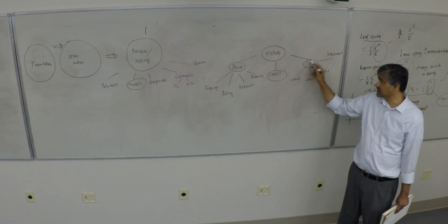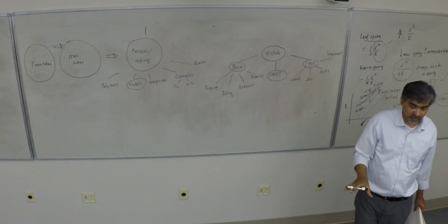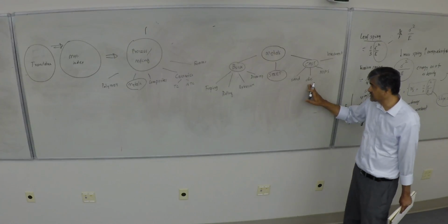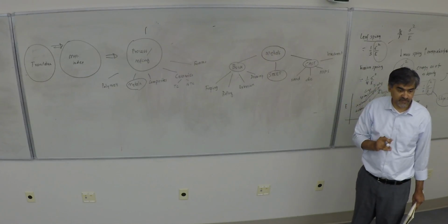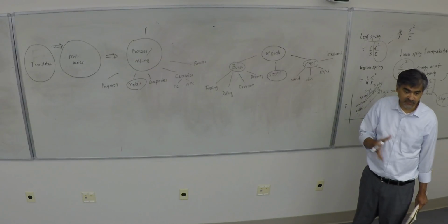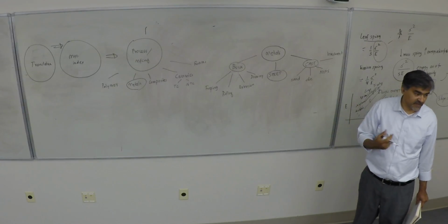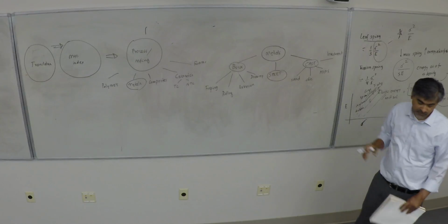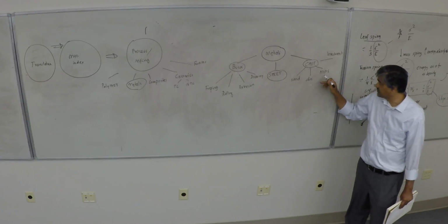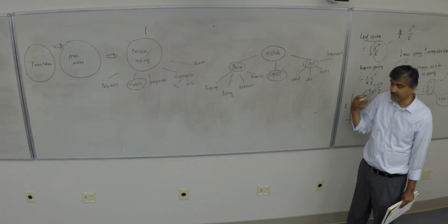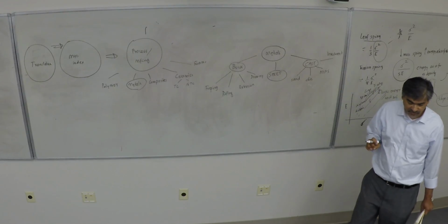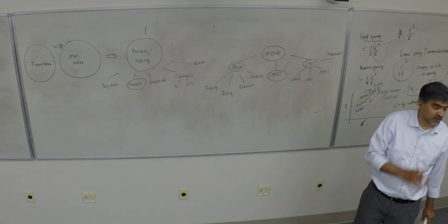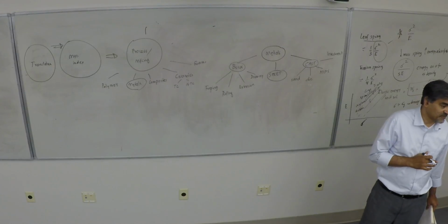Sand casting is of course your basic casting. Prepare a sand mold, you pour your metal, the mold gets destroyed, you pull out your finished part. Die casting is very much like injection molding, where you have a closed cavity, you push metal in and form the parts. So very niche parts, high tolerance, but essentially cheap as well. Then the HIP is particularly to avoid the voids in the casting: you have a blanket of nitrogen or argon on the cast melt, and with the pressure you are able to collapse those voids.